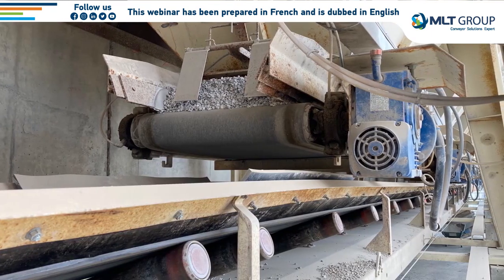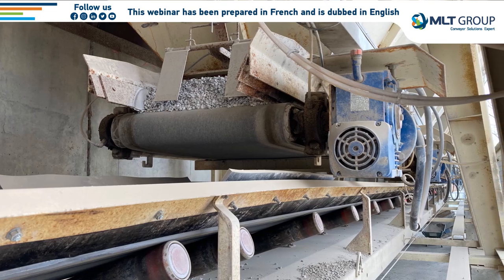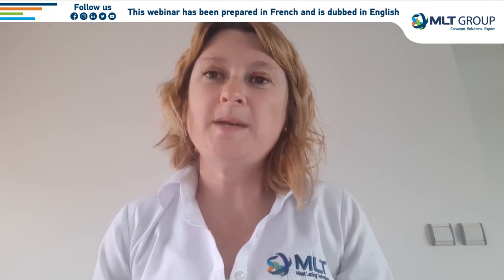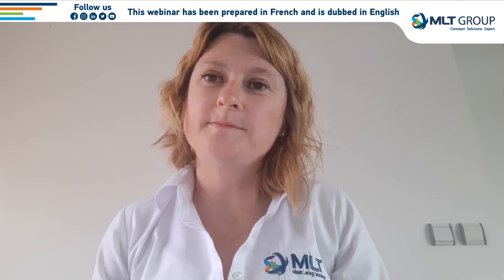As you can see on this picture, the belts turn around small rolls of only 90 millimeters, given that the minimum roll diameter amounts to 250 for the smallest carcass. Therefore, the spliced belts cannot turn on such small rolls, their carcass is not suitable, their lifetime is greatly reduced, and the splices open after only a few days. That's where MLT expertise and technical belts come in.